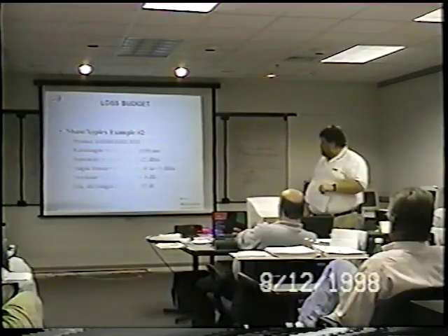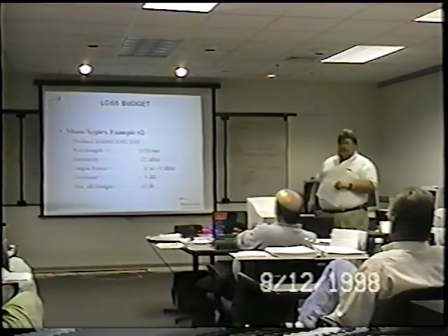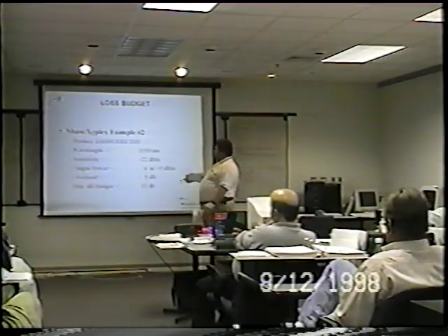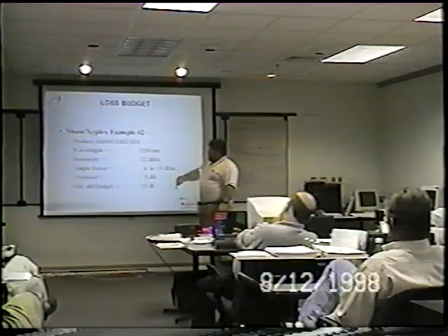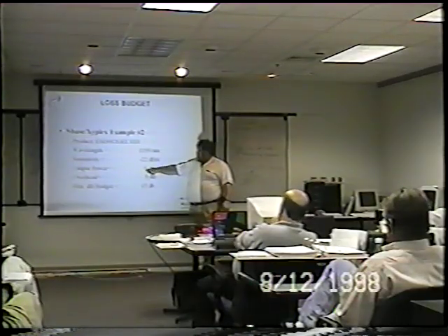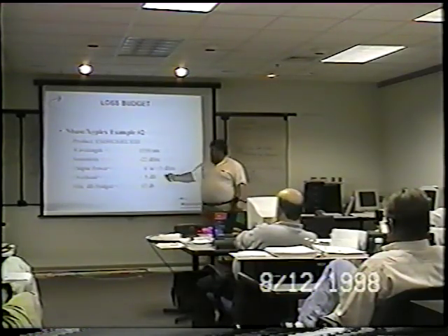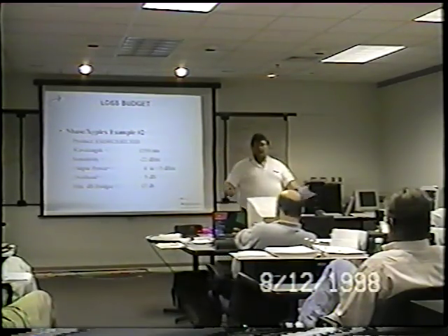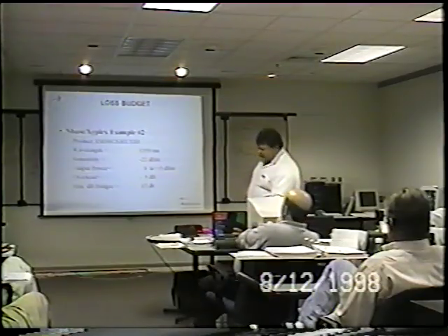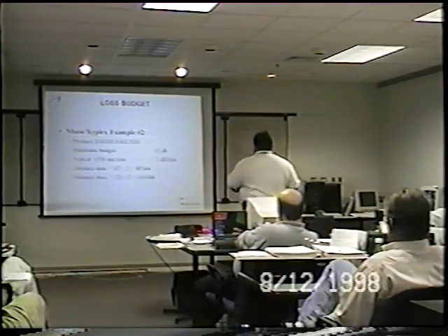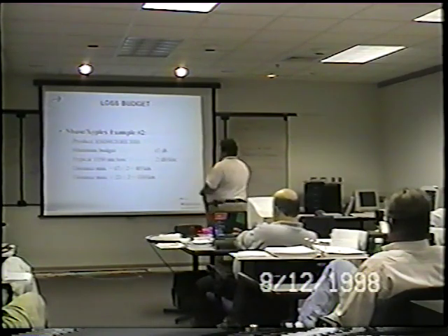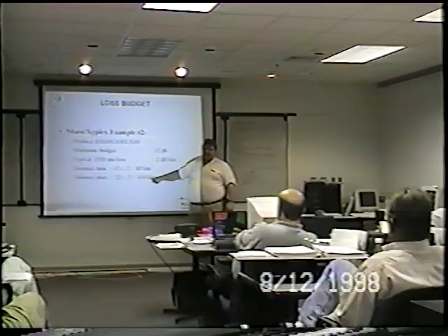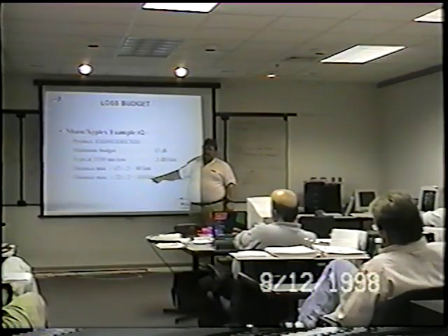Another example, let's take a look at some of our S3 carrier type sockets at 1550 nanometers. Sensitivity of that receiver is -22 dBm. The output power range is from 0 dB to +5, minus 5 dB of overhead. My minimum dB budget on the S3 pair is 17 dB, and that results in a range, basing my link loss at 0.2 dB per kilometer, of anywhere from 85 to 110 kilometers.